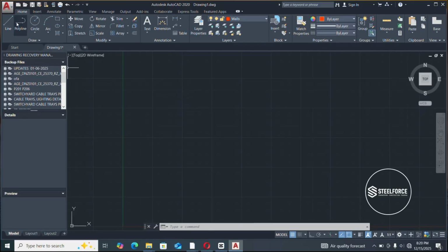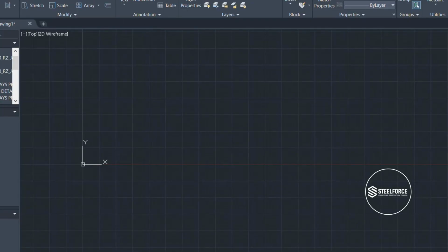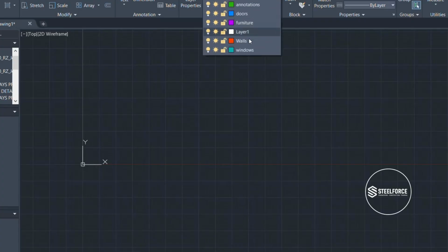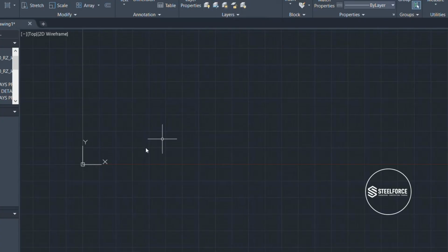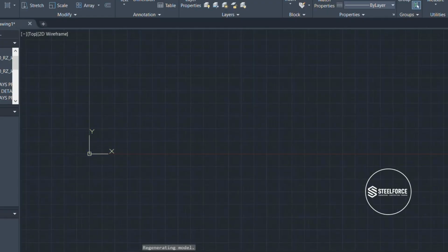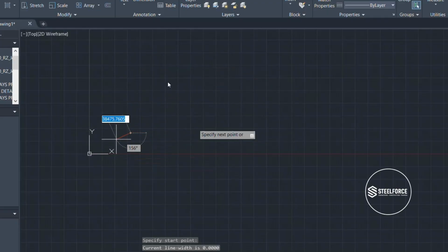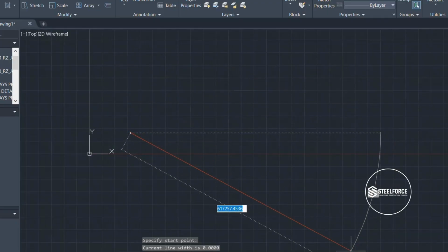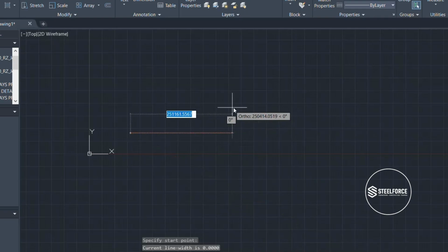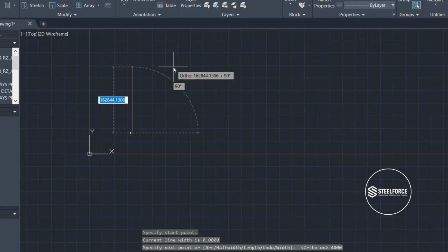So we are going to use polyline. Okay, so now to draw walls, we click on walls command. Then we click on polyline. See, it appears in the form of a rubber band. So we either click on auto mode or press shift on the keyboard. So we want a wall of 4000 millimeters by 4000 millimeters.